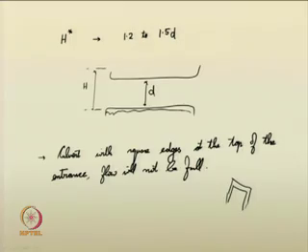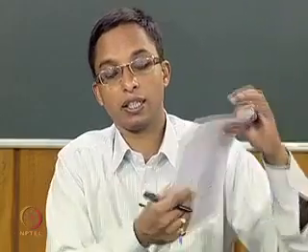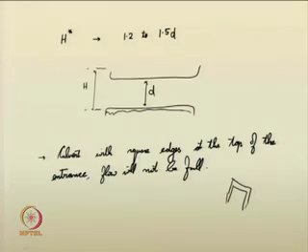Mostly the flow will be below headwater level. Even if the headwater is above a certain value in such square conditions, it will dip inside, it may give an orifice type of flow inside the barrel of the culvert, and then exit from the outlet portion of the culvert. Such situations can form, or it may act like a sluice gate.